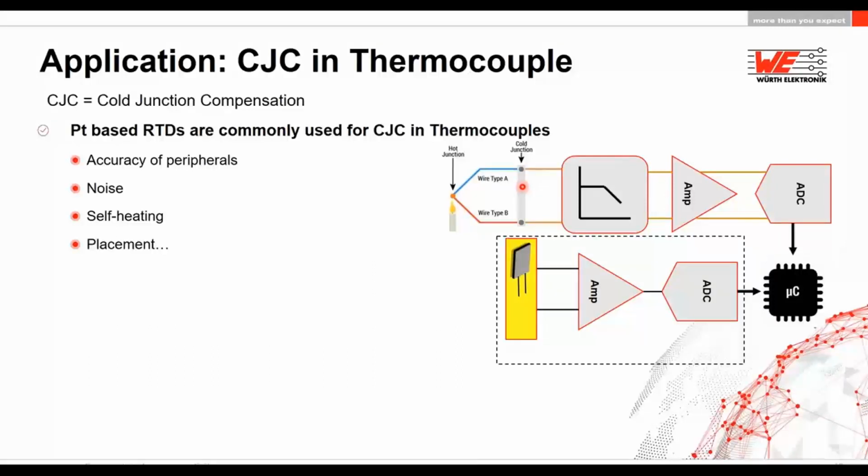So here, when you say that my sensor has an accuracy of X percent, then you also add some peripheral devices, for example, filters and amplifiers, which add some noise and also add inaccuracy to your complete system. So at the end, sometimes you have to recalibrate your whole system. The RTDs might also have a problem of self-heating, and they are also very design sensitive. So you have to take care of your design and invest a lot of time designing complex circuits.